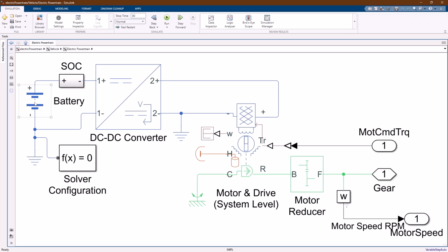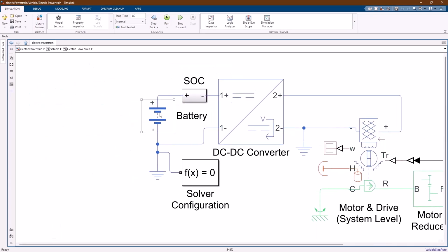However, as a starting point, this simplified battery lets us get up and running with the ability to increase complexity of the model later. Because Simscape will handle how our components are connected in our schematic for us, all we would have to do is remove this battery model and place a new block that represents our more complex model in its place.